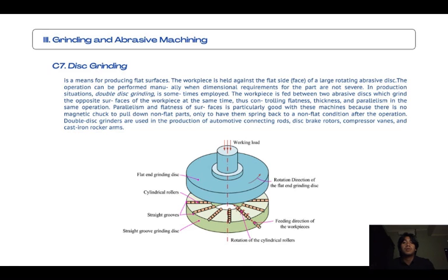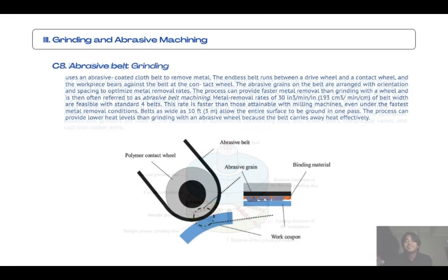AFM is particularly useful when the area being machined is not accessible for other methods. In practice, two cylinders on opposite sides of the workpiece are used to contain and pump the medium, which flows back and forth repeatedly through as many as 100 cycles until sufficient material is removed from the workpiece.